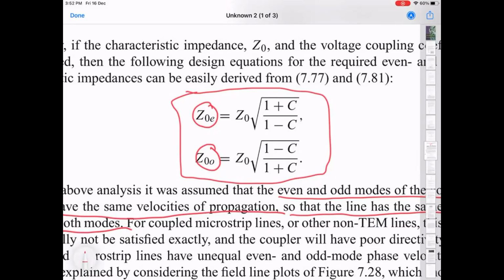Now you can think of this the same way: okay, this is odd mode excitation, and these are two individual transmission lines of 50 ohm each. Then according to this, it's supposed to be 50 ohms, right? The fact that I have not put any transmission lines here doesn't really matter. It's going to be a 50 ohm transmission line.